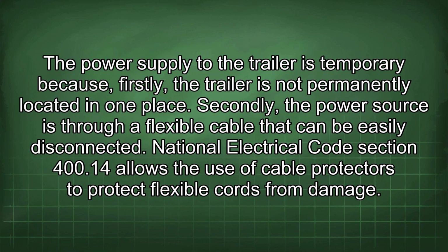The power supply to the trailer is temporary because, firstly, the trailer is not permanently located in one place. Secondly, the power source is through a flexible cable that can be easily disconnected. National Electrical Code Section 400.14 allows the use of cable protectors to protect flexible cords from damage.